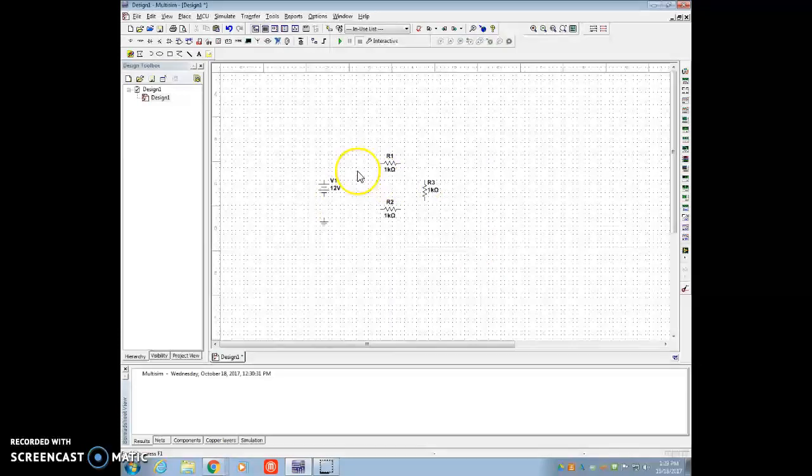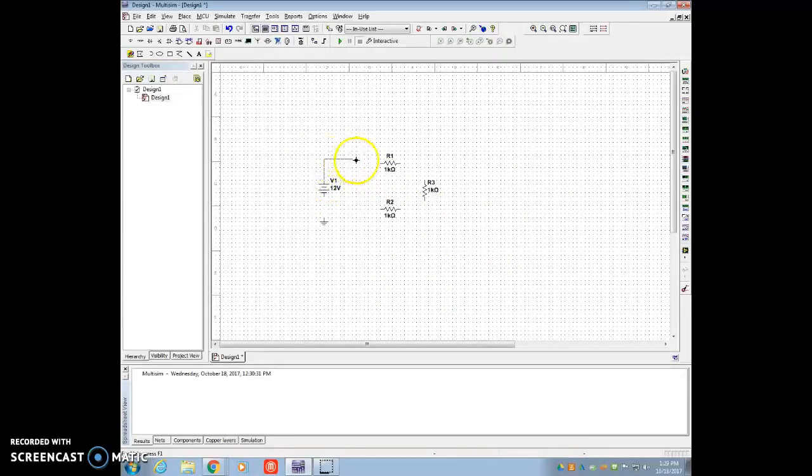To add wire, I also show you how to do that in the tutorial. You just click on the first end of the component and click to finish the wire, and it'll turn red. So click and click. I also show you that if you want to tell Multisim where to place a corner, you can do that by clicking, and then I could make it end over here. Hit escape if you don't like what it's doing. I'm going to just click, click to here, and then click, click over here, and then click from the ground back up to the bottom of the power supply so that I have that node. Okay, so this is our first series circuit.